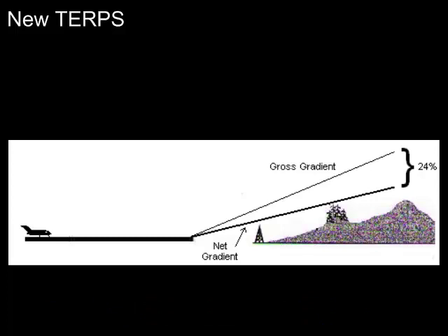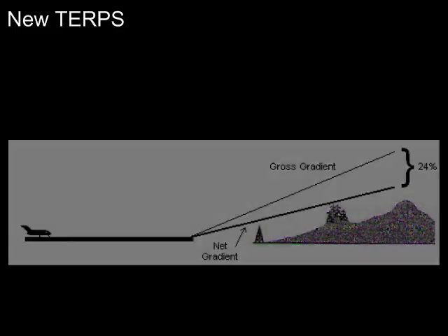So how do you determine if the departure is 0.8% or 24%? All departures not created by the FAA are 0.8 types. Within the U.S., it's a mixed bag. Roughly 60% are new TERPS. The pilot needs to examine the departure plan, a step he or she is already doing, to determine the telltale signs of new TERPS procedures.